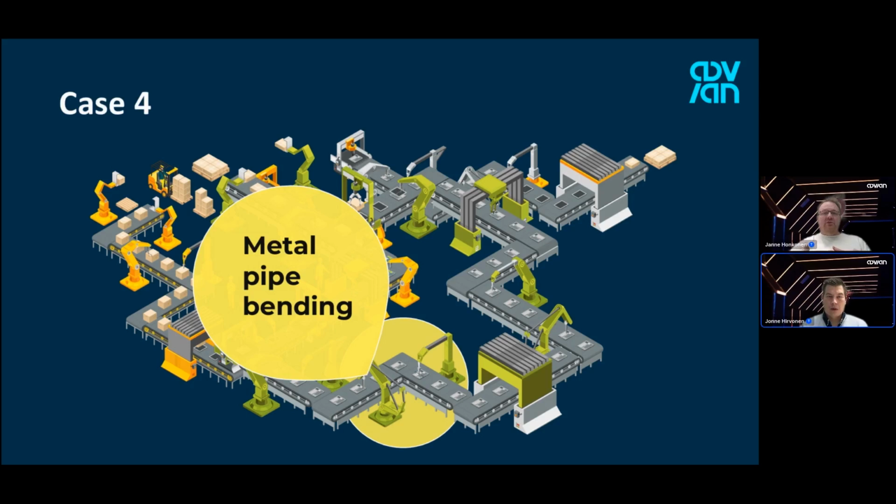The inspection of the pipe itself must be done in 3D. So we utilize once again 3D stereo cameras to create a 3D model of the pipe in real time. Then this created model is compared against CAD drawings or STEP model, wherever is available, and the given tolerances, which are allowed for changes on the plan.